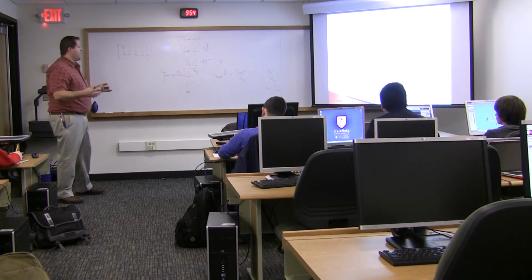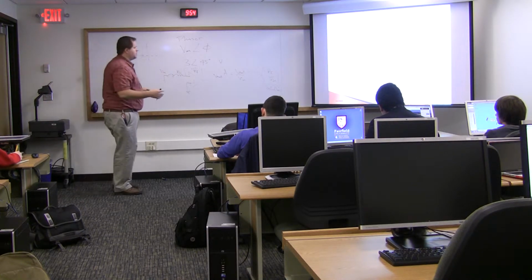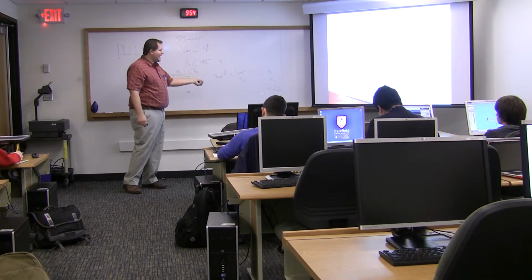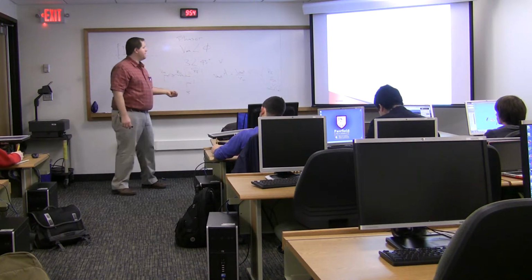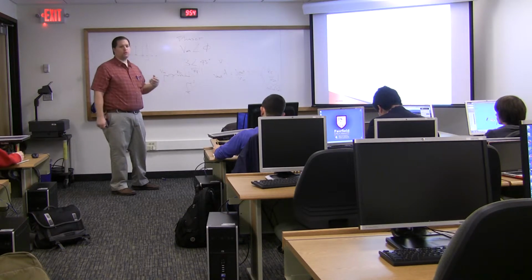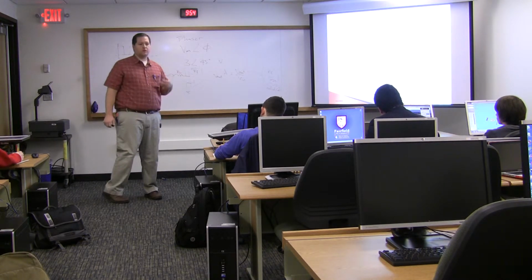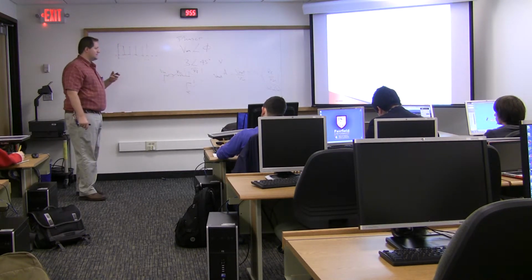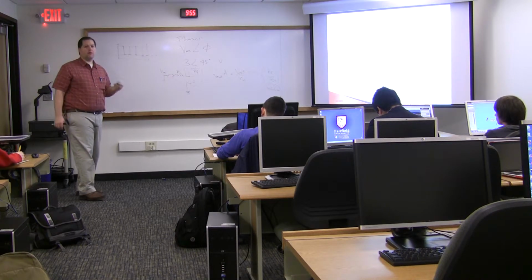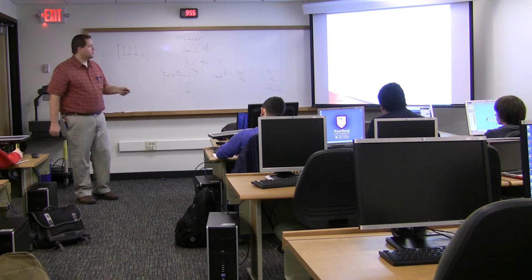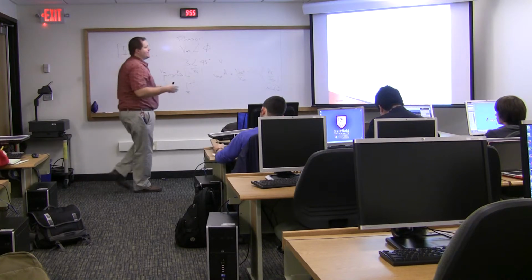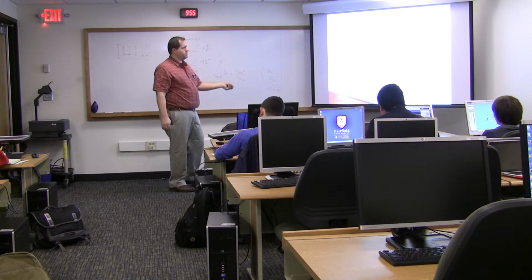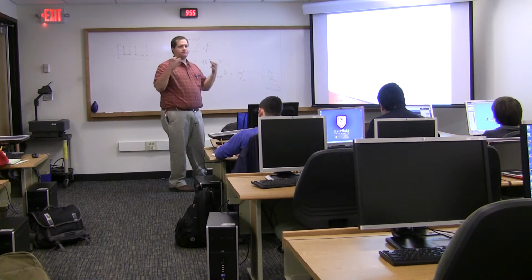So now imagine that that has the omega in it still. This gain is now a function of omega. This is our transfer function. So the transfer function is defined as the ratio of the output to the input. If we look at this as a simple block diagram, inside this box there's a bunch of circuitry.